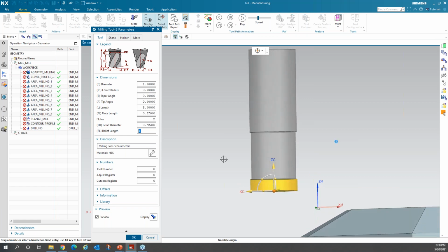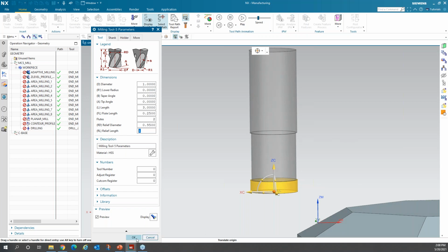Whereas before you just used the regular end mill and turned off your gouge checking and inside because it's going to be rubbing. Well, now you don't have to turn off your gouge checking. You can let things go as the safe route, the way they should be.